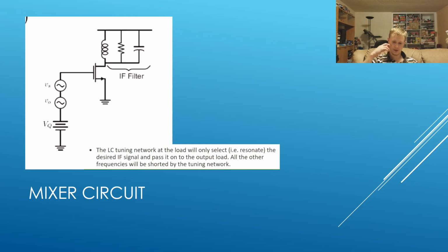We just use a transistor, like the one in the diagram, to mix the two analog signals together. This single transistor does the mixing, amplifies the signal, and the LC load of the circuit works as a filter. So the amplifier, mixer, and bandpass filter from the block diagram are all contained in this single circuit. But there is one problem with this circuit.